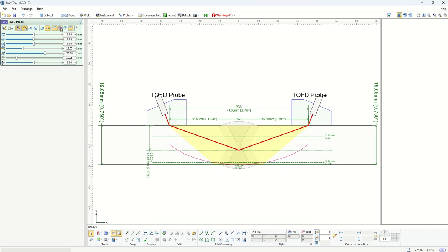And finally, the other one would be the very important information, which is the dead zones on the ToFD. We know that when you design a ToFD technique, you should always be aware of your dead zones. The dead zones are two regions close to the surface and the back wall.